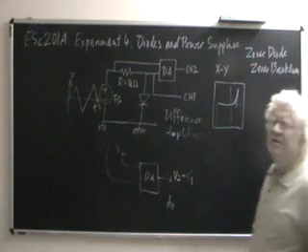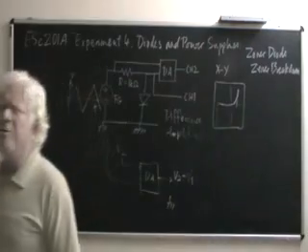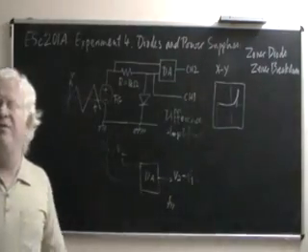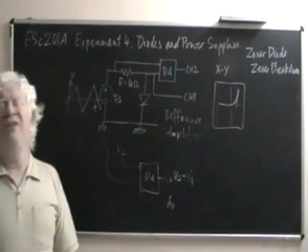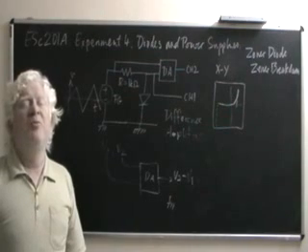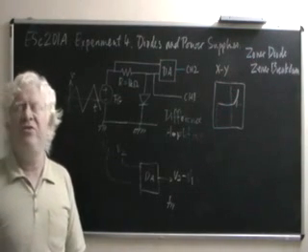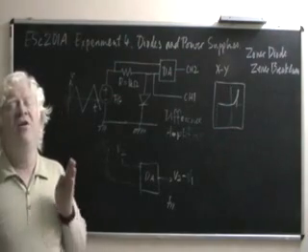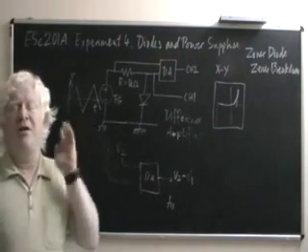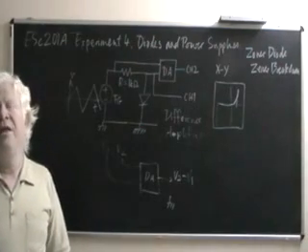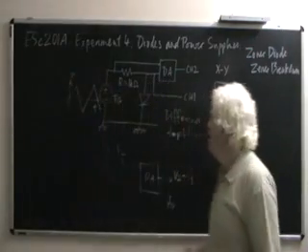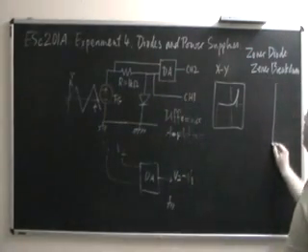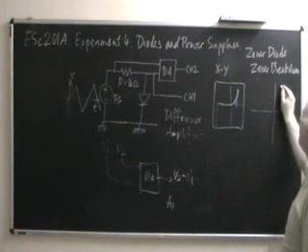The Zener breakdown is a repeatable phenomenon. You can Zener break down a reverse Zener diode any number of times. And one of the very nice features that a broken down Zener diode possesses is a very, very constant voltage irrespective of current under breakdown conditions. In short, its incremental resistance under breakdown is very, very small. Let me plot a Zener diode's characteristic for you. Not necessarily to scale, but indicative.